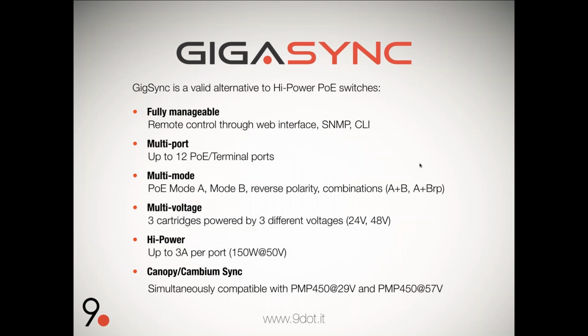It's also multi-mode, so you can power every kind of PoE devices with mode A, mode B, reverse polarity like Cambium does, combination of these modes, and for example, you can power different devices like 48 volts PoE devices, 24 passive PoE devices, and every kind of device you want to power through PoE, of course.